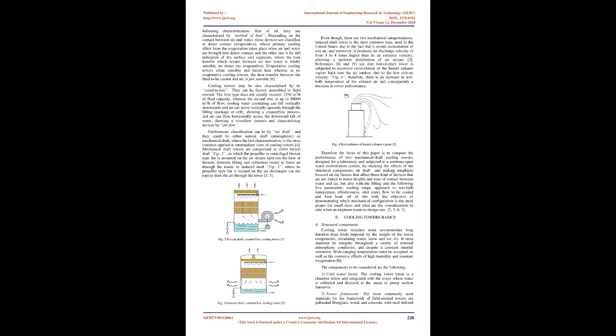from the evaporation takes place when air and water are brought into direct contact, and the other one is by full utilization of dry surface coil segments, where the heat transfer which occurs between air and water is totally sensible, indirect, non-evaporative. Evaporative cooling towers relate sensible and latent heat, whereas in non-evaporative cooling towers, the heat transfer between the fluid to be cooled and air is just sensible.